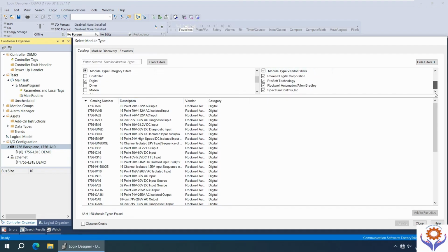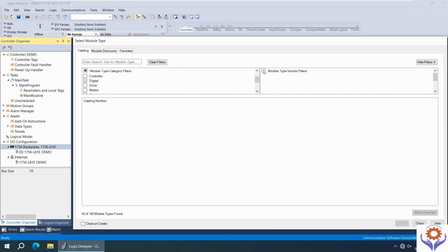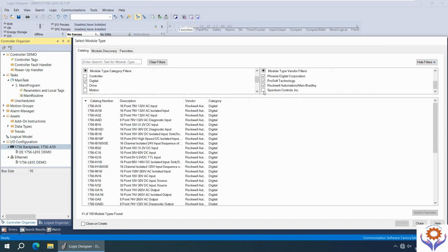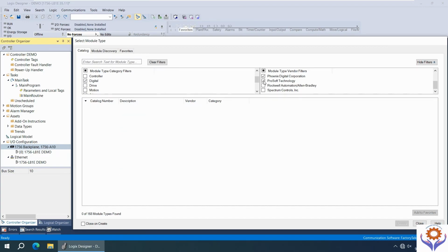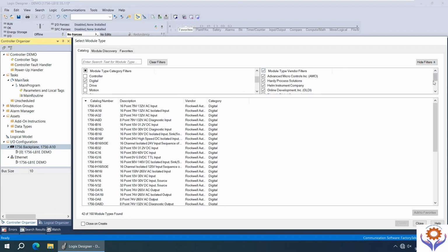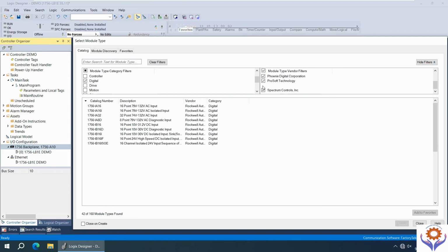See, here you can find AC inputs, DC inputs, and also some of the TTL inputs, etc. So you need to select your IO card. If you have the bill of material earlier, you can directly type your part number, it will appear here directly. But in our case, just on the right side, you see all these digital modules, they will be selected with Rockwell Automation or Allen Bradley PLCs.